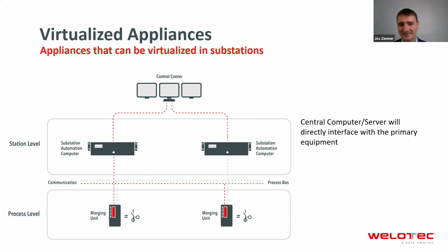But this is not the end. Before we talked about the station level that you can virtualize today. But if you're looking at the process level where you have the primary equipment, it can directly interface with computers. So you don't need any bay level anymore where you have your IEDs. You can run them as a virtual machine on the devices.